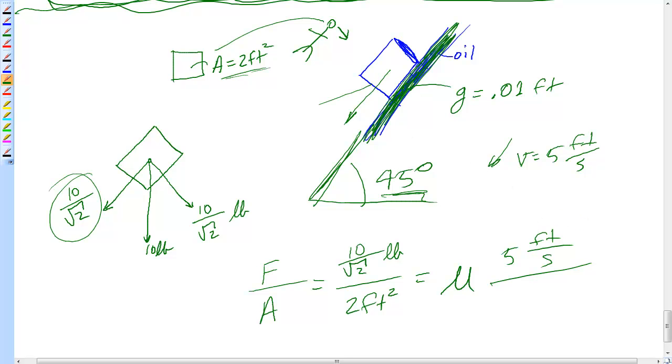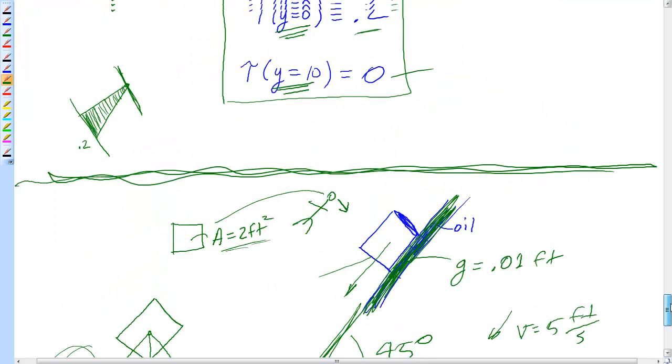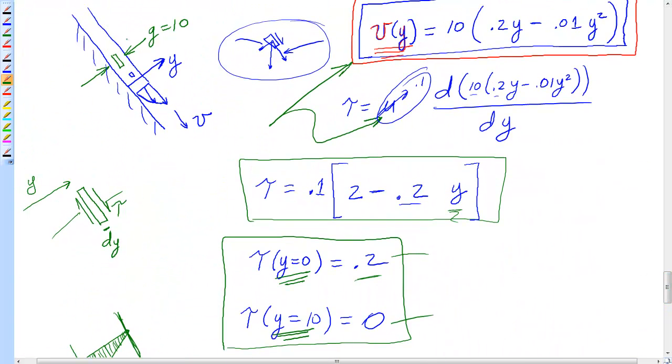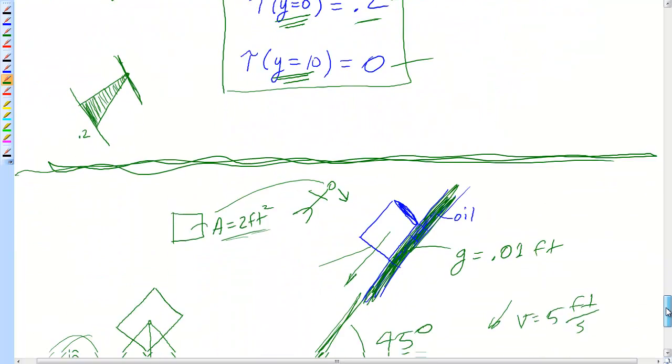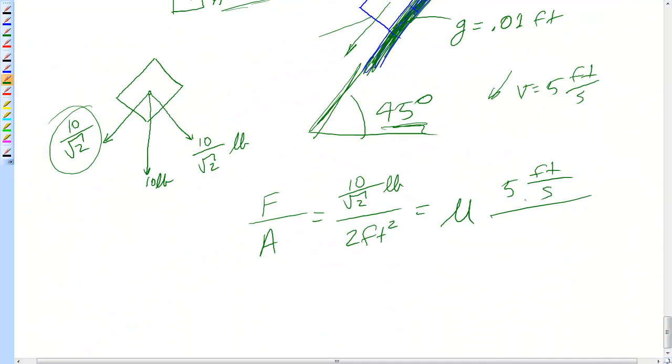Now it is true that there are forces on the particles inside this layer, just like the previous problem. However, now I'm putting something on top of this and pulling it quickly. So if you pull it quickly, yeah, there still is a parabolic profile, but it becomes very, very minimal compared to the linear nature of the flow distribution, and you can assume it to be a linear distribution.